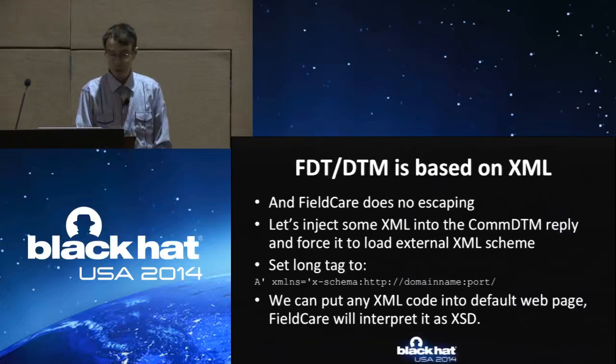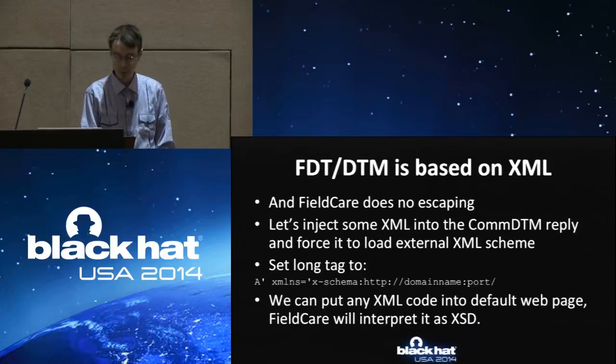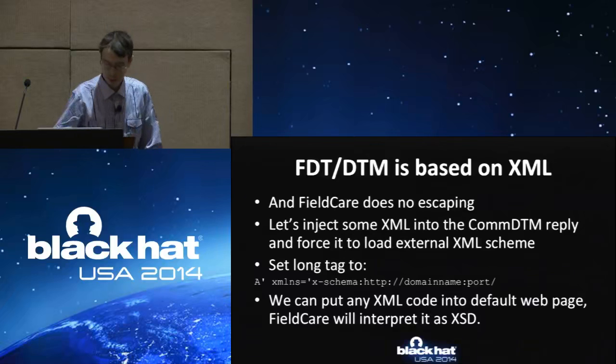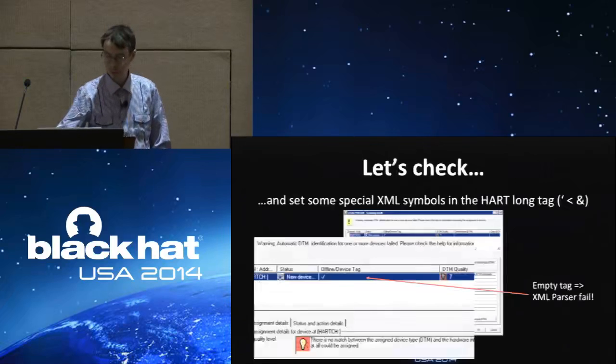Field care does no escaping, and FDT DTM applications are XML-based. So let's inject some XML code into the COM-DTM reply and force it to load an external XML schema. We can do this by changing the field device long tag or forging field devices. Using this method, we could inject a request to an external XML schema on some remote web server and send back custom XML code of any size.